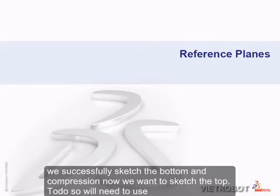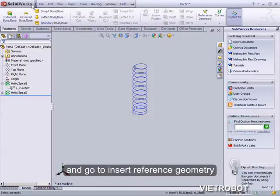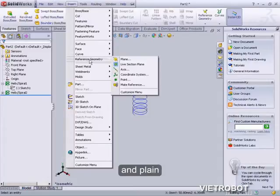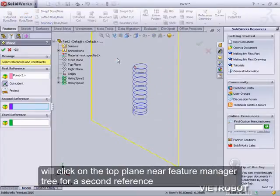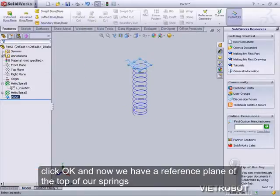Now we want to sketch the top. To do so, we'll need to use a reference plane. We can insert a reference plane to our helix by clicking on the top endpoint of our helix. Then go to Insert, Reference Geometry, and Plane. We'll click on the top plane in our Feature Manager tree for our second reference. Click OK, and now we have a reference plane at the top of our spiral.